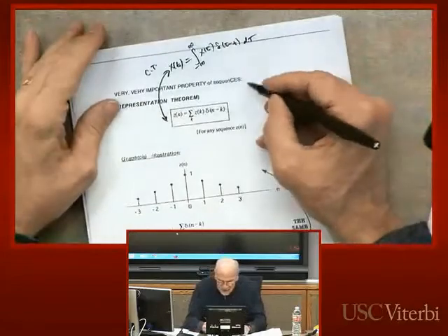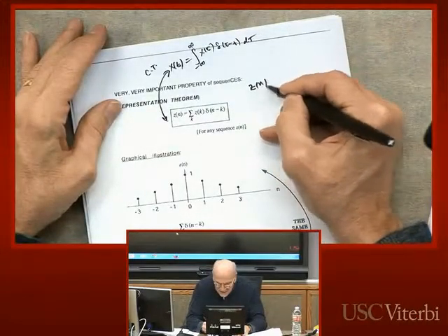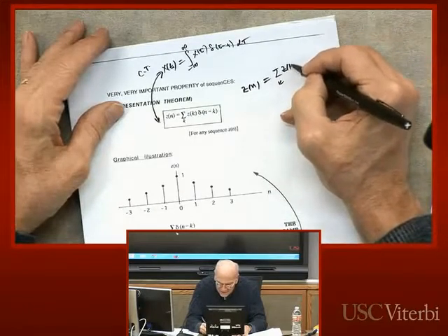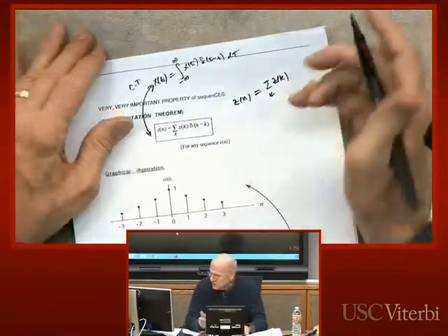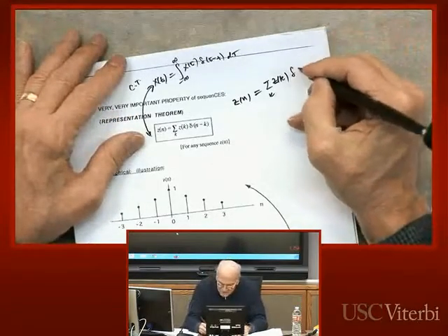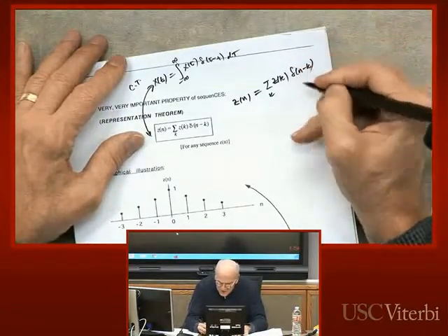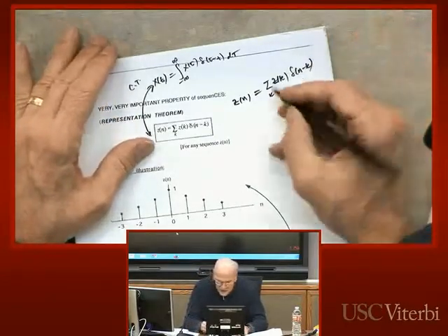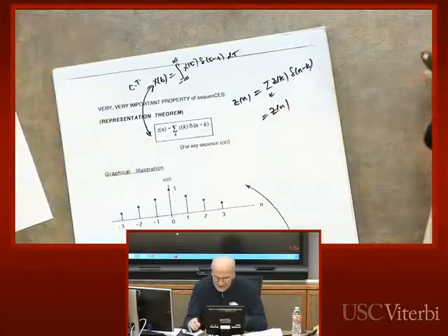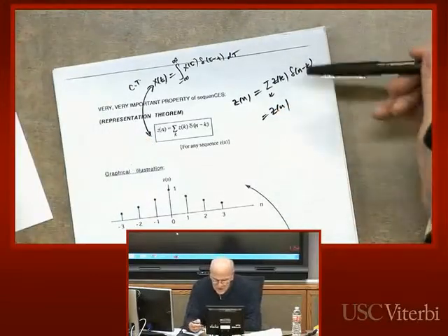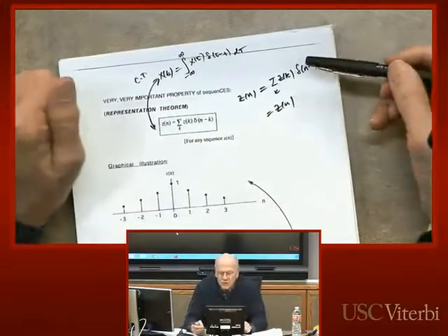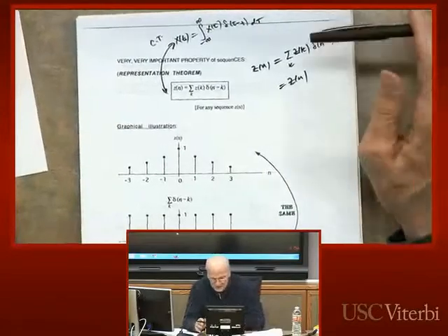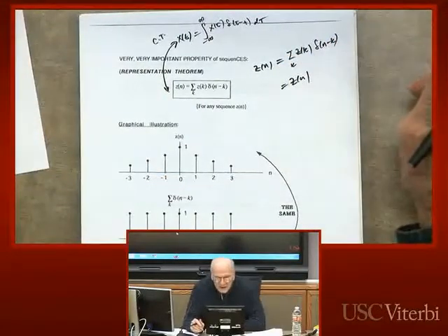And essentially what it says, if I have a sequence, I can write this as a summation over k, and this will become important when we talk about, in just a moment, certain types of discrete time systems, the systems called linear time invariant systems. And that's all it really says. Obviously, it's trivial because delta of n minus k is only non-zero when n equals k, and so you get z of n out. So it's just a basic identity.